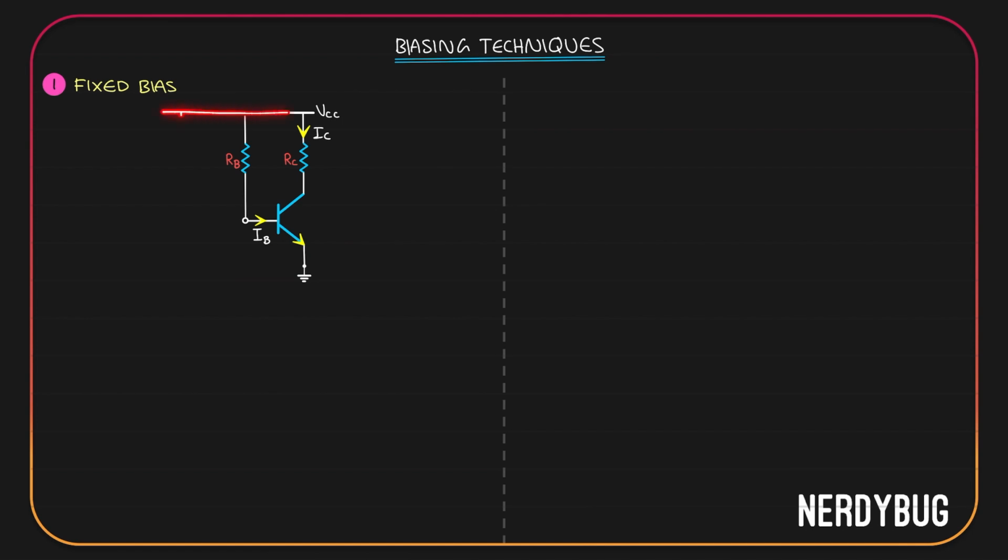VCC can be modeled as a cell of potential VCC like this between the topmost point and the ground. That means we have one more loop like this through the base and emitter. So we can call this the base emitter loop. So basically there are three loops. To make the loops more visible, let me draw the circuit in a different way like this.